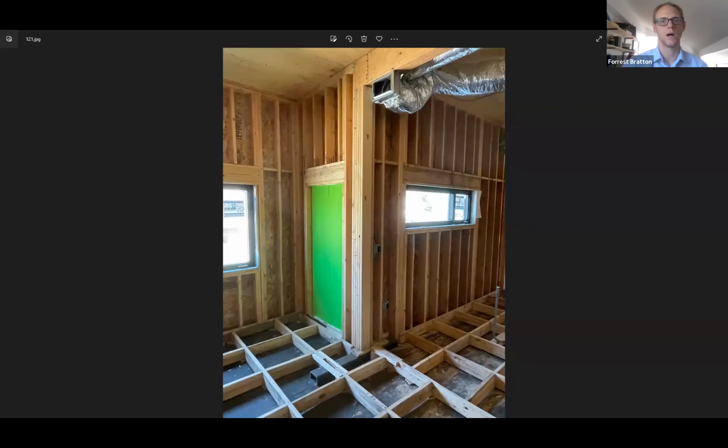I want to say the total load per square foot on those panels was on the order of 250 pounds per square foot, a large area load, or smear load, we call it. Bumping that up by 20% was just more than we could do with the system as designed. It would have meant a pretty wholesale change in how we design it, because the concept was to keep the panels alone doing the spanning, and they cantilever off the ends of the building past the girders as well.